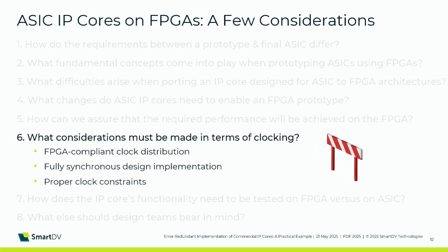Then when it comes to clocking, this is a major difference between ASIC and FPGA structures. The clocking structure must be suitable and typically also must be adjusted to suit the FPGA clocking.